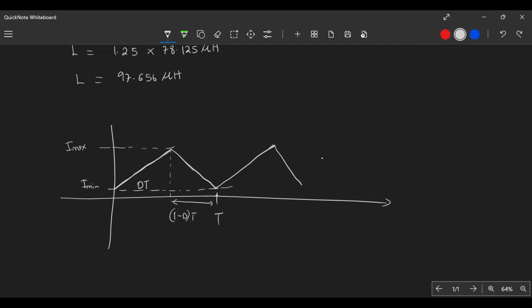So that's how the waveform looks, right? Okay, so we need to find those currents. The first current you're going to have is from 0 to D times T, this time period here. And then another portion of current is this one here, discharging, from DT to T. So we need these two piecewise equations.